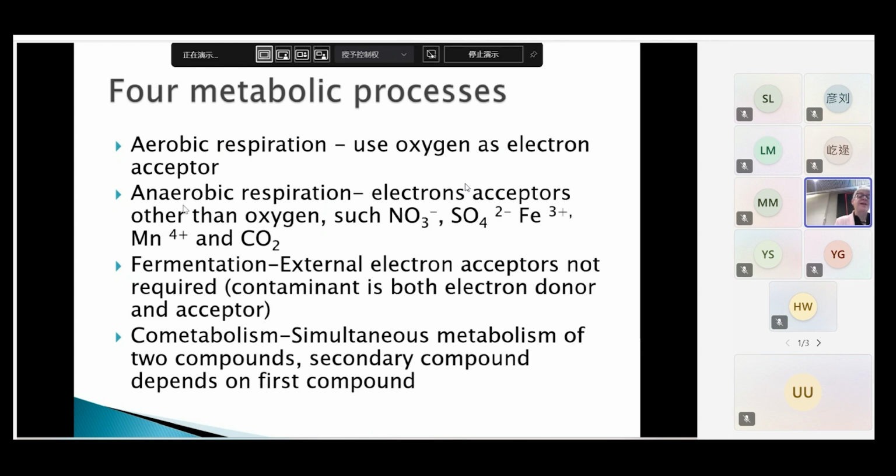So, a more extreme process is doing vitrification. Basically, what you're doing is you're putting a current into the soil and you're actually melting the soil. It creates a very high temperature situation, and that's how you're able to melt the soil, because basically you're subjecting the soil to about 1600 degrees Celsius.